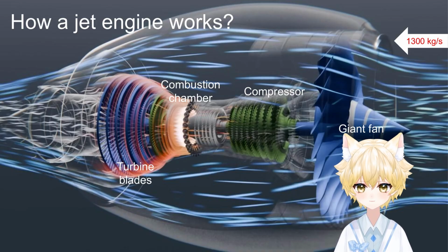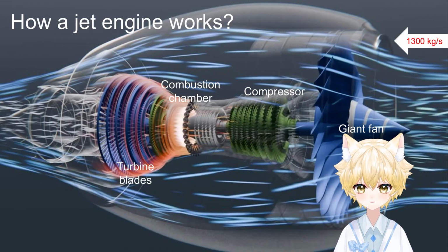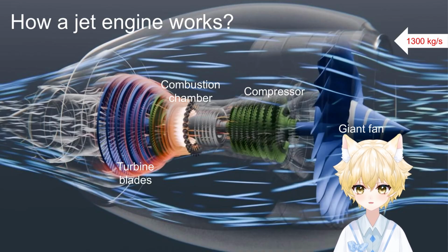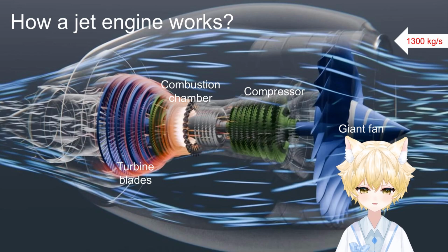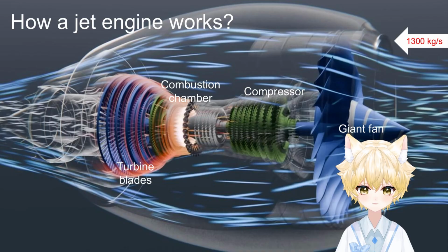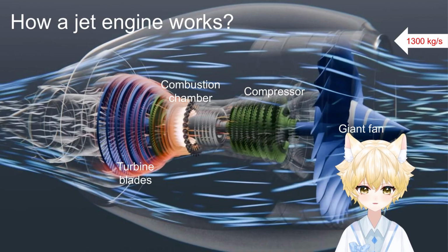As the gas rushes through the turbine and nozzle, its pressure drops from around 50 atmospheres down to 1, and it expands by almost 20 times. And that spins these turbine blades up to 12,500 revolutions per minute.